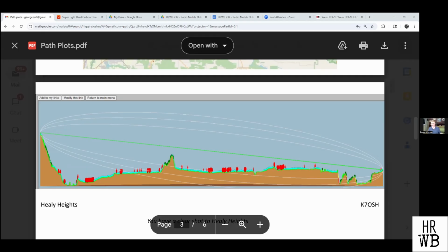In the case of free space, you can imagine two spaceships that talk together in the openness of space. There is no obstruction in any direction. This is free space. When you are above the ground, that never happens. There is always a portion of the space that is blocked by the ground. And if you look at the effect of these obstructions, you don't have all the energy that you would receive normally if you were in free space.